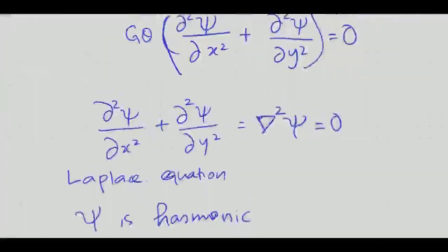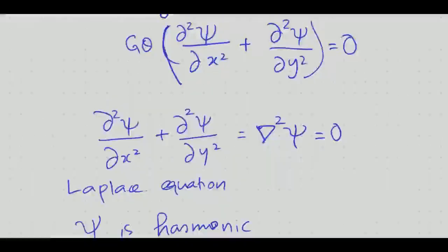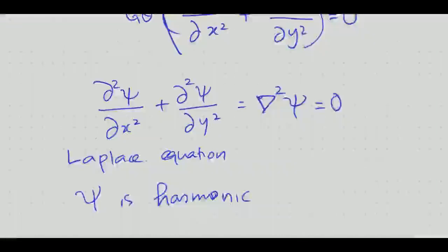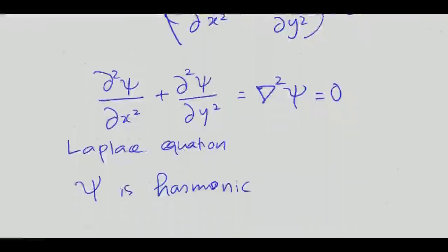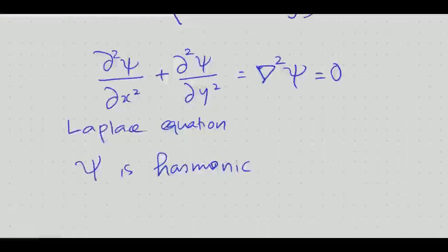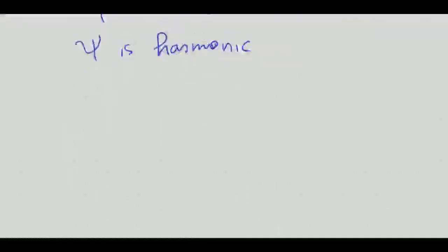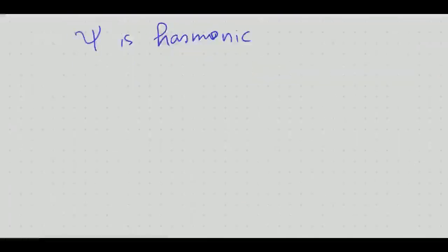So now if we take any cross section, maybe rectangular, triangular, or elliptical, or any other irregular shape, in all those cases the warping function should be such that it is a harmonic function. So now we will move into boundary conditions.